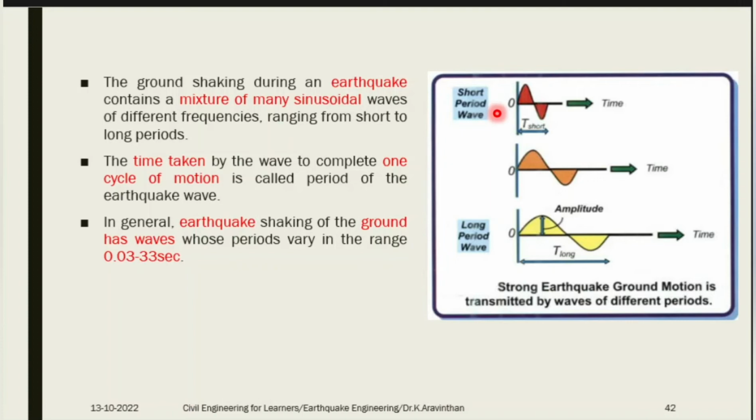What is the purpose of finding the time period? Why do I need to find it? There is a concept of resonance. The earthquake targets the building in the form of waves. One single wave is coming and targeting your building. Your building also has a wave, called the time period.